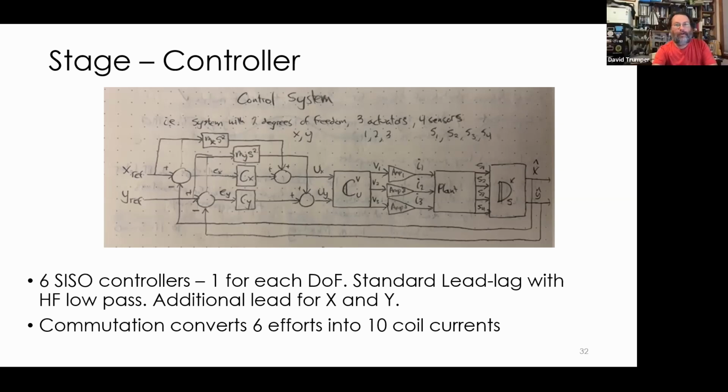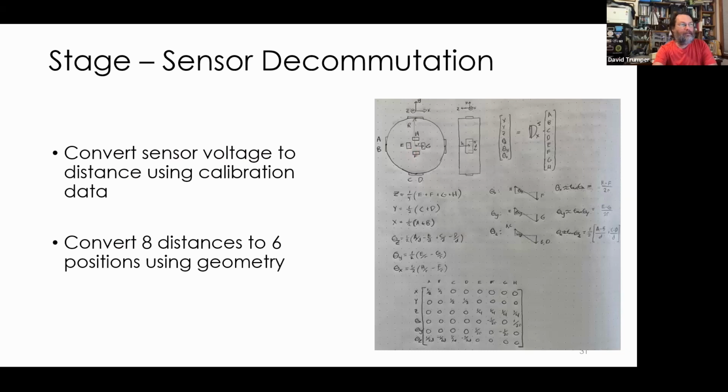By the way, could we go back a slide? Yep. I would call it decoupling rather than decommutation, just because commutation has this sense of motors. Right. Okay. Just linear decoupling. If you think of rigid body for small angles, you can just take differences in simple ways, and sine theta becomes theta, and all that becomes this. So they're just simple linear transformation matrices for small rotations.